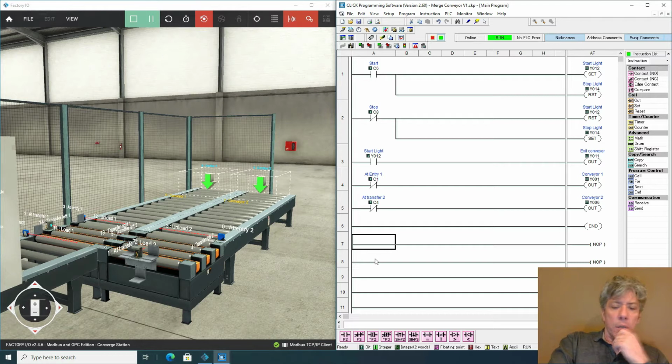So in order to realize that I need to move it forward and therefore turn on these rollers, I think what I'll do is say, if there is a pallet here, but there's not a pallet at the transfer conveyor, then get one there. Turn on the loading rollers and make it happen. So how do I say that?